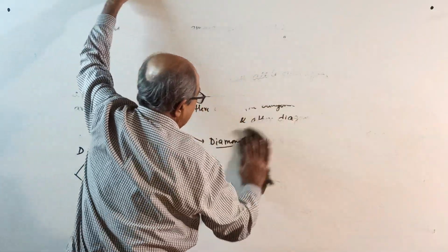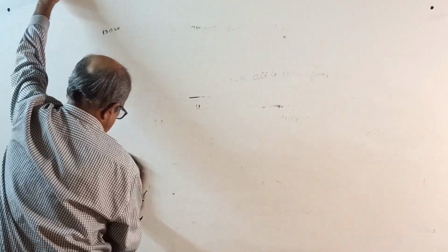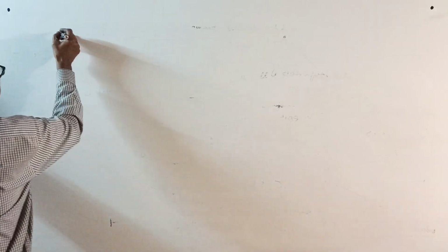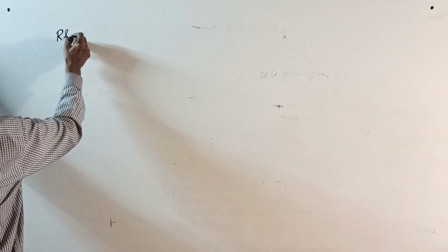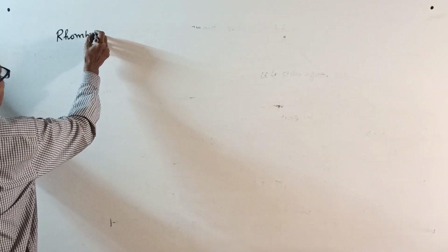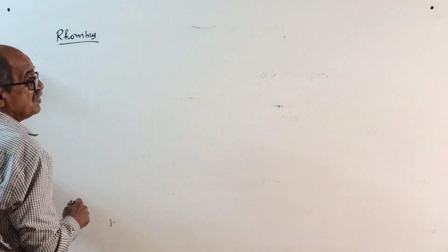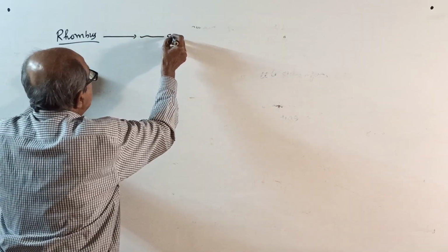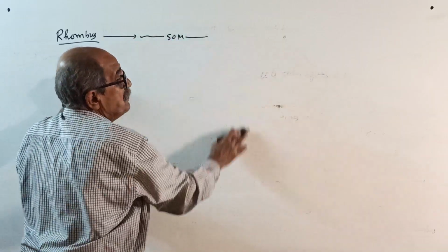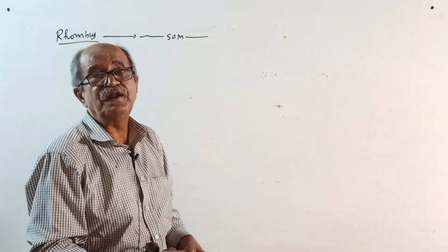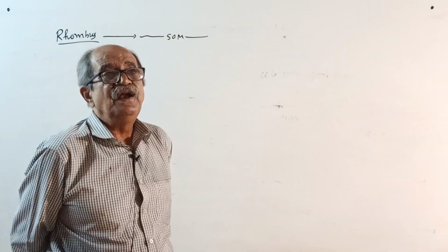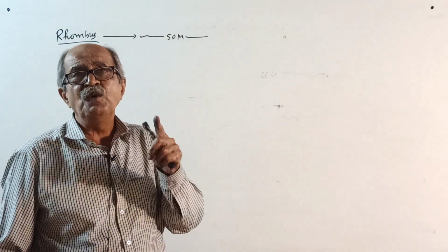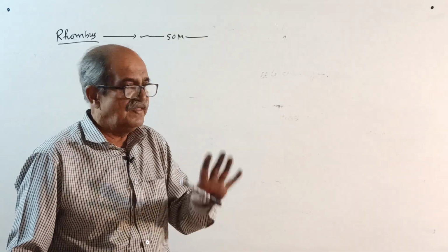To understand correctly, make this note. First consider rhombus section. Property of the rhombus here. Make a note. What usually in strength of materials, or plastic analysis, we write, rhombus means it's a square section which is placed with one of its diagonal horizontal, other diagonal vertical.